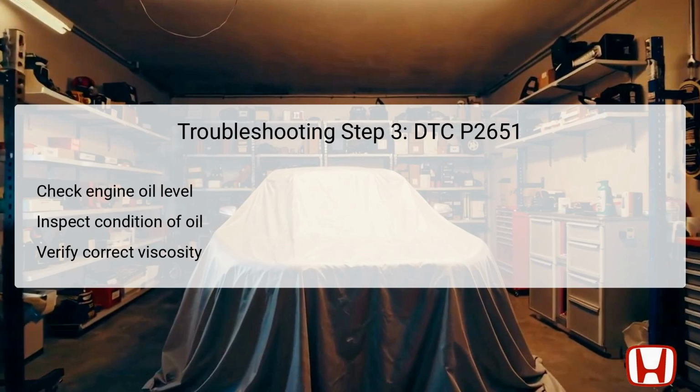It's also necessary to verify that the engine oil being used meets the manufacturer's viscosity requirements, as incorrect oil viscosity can significantly affect engine operation. Ensuring all these factors are optimized helps rule out issues related to oil supply that might trigger the DTC.